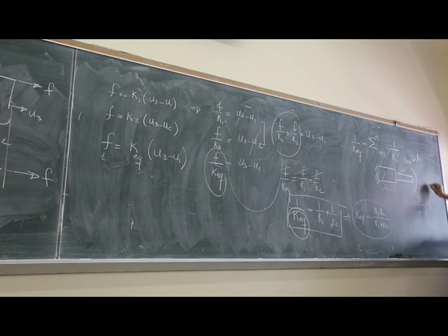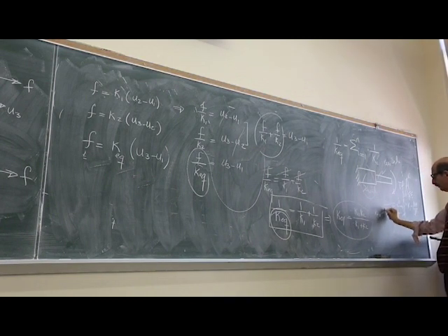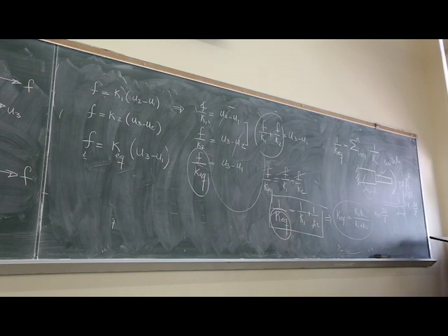If the displacement is PL over AE, and the stiffness is defined as the force that generates a unit displacement, so K for a bar is AE over L, and for a shaft, KT is JG over L. So in order to replace these two with a single shaft, I can just write 1 over KT, the torsional stiffness that we want to find, would be 1 over G1 J1 over L1 plus 1 over G2 J2 over L2.